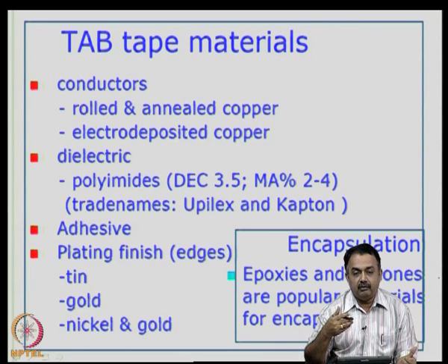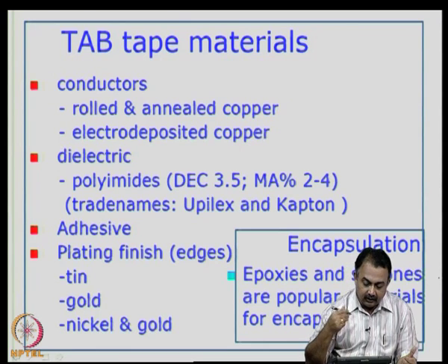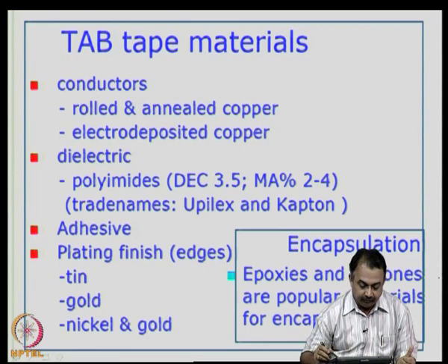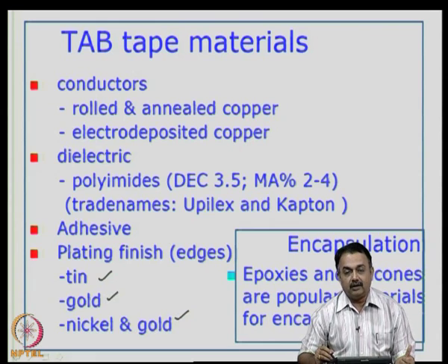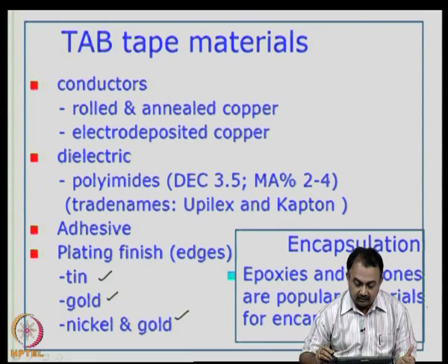So, you require a very good adhesive to hold the lead frames onto the tape. So, different adhesives may be used, and then the plating finish for the lead frames could be either tin or gold or nickel and gold. Obviously, you are looking for better contact resistance, and therefore, you have a wide variety to choose from.